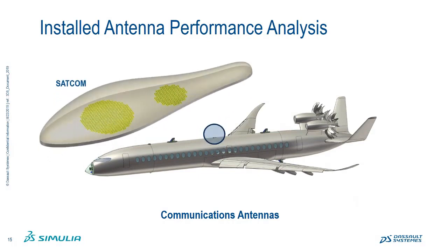We were previously discussing the satellite communications antenna, which includes 2 circular-shaped microstrip patch arrays. We will place the arrays with their radome on top of the aircraft to check the installed performance. As mentioned previously, the satellite communications array uses beamforming to point the beam in different directions, which is used to track satellites during flight and maintain a strong communications link.